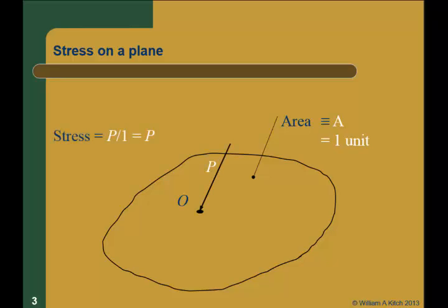And then we can have some forces acting along this area. Theoretically, I could draw this as a stress distributed all across this area. We're just going to use one little arrow because drawing lots of arrows is hard. But the stress in that area is this total force, P, divided by the area, which is 1, so it's just going to be P. That's why we use an area of 1, because dividing by 1 is easy. So that's the concept. If you read engineering mechanics texts, these are called tractions.